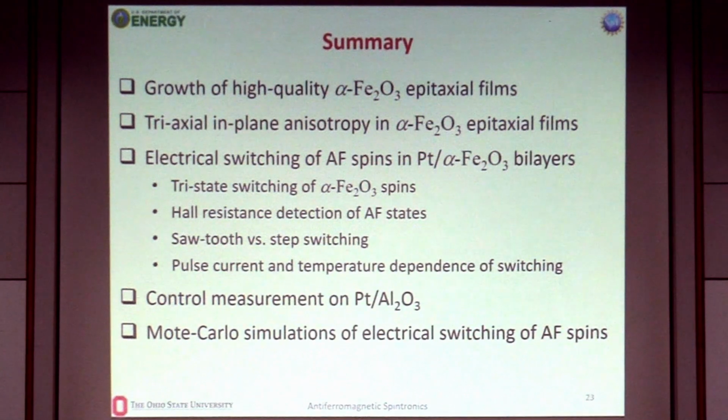So maybe I can comment on that. This is exactly the same as what we also see in our platinum manganese nitride experiment, and it's related to the grain size distribution that you have. So this is what I've shown, that you always switch the same delta depending on the temperature, and that means that you basically select different grains with the spin-orbit torque strength that you have available. And then when you have a thicker film, you just switch narrower grains. So the volume is still constant. So you saw something similar in the manganese nitride?